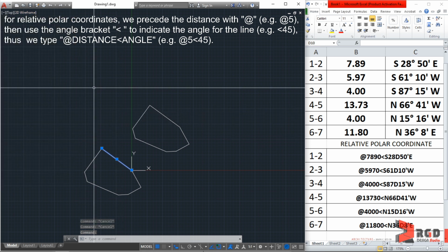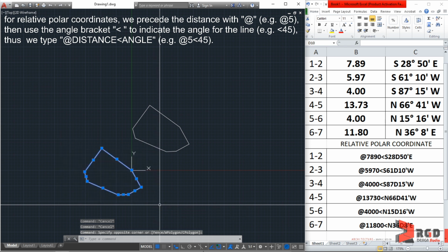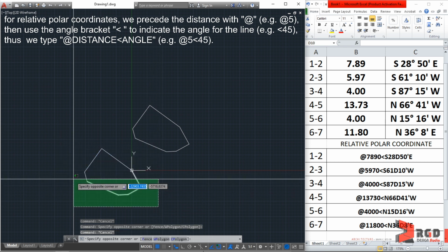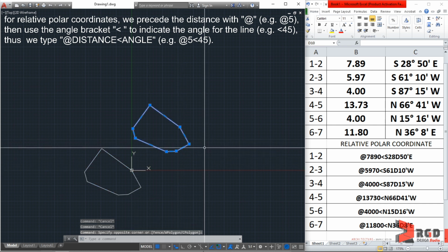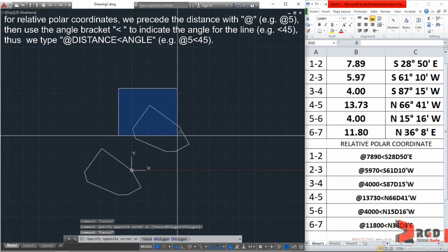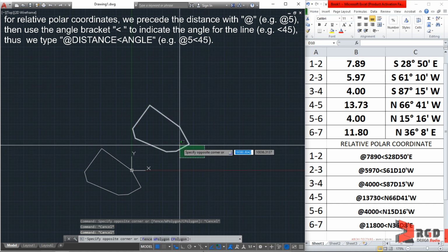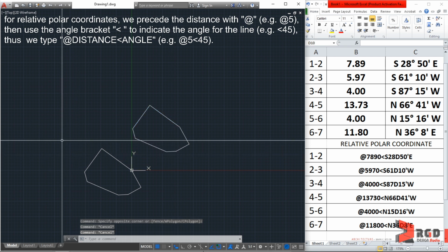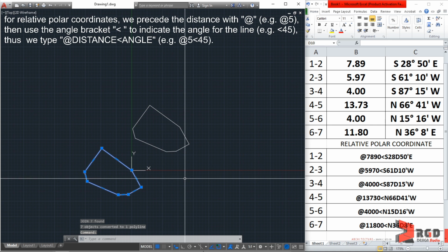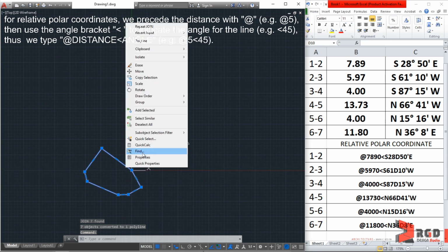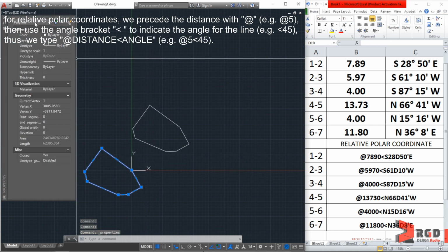However, to select them, you could select it through a window selection or crossing selection. This one, just simple crossing selection. Could easily be selected all of the geometries of the lot line. But we could also select this one, and then we just type J to join the geometries. Enter. And now when we go to properties, it's now a polyline.